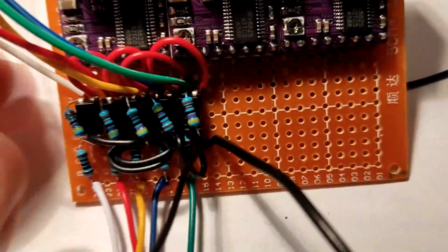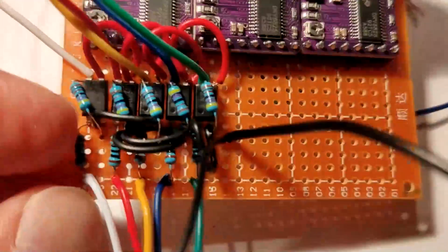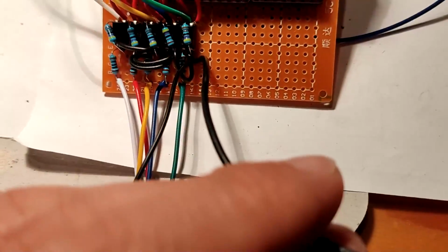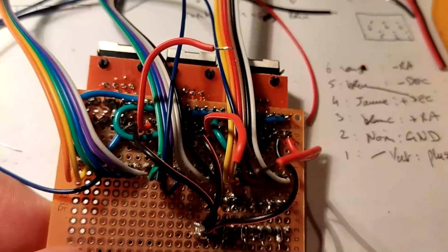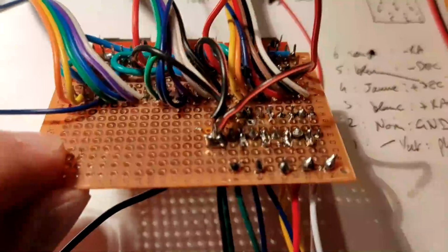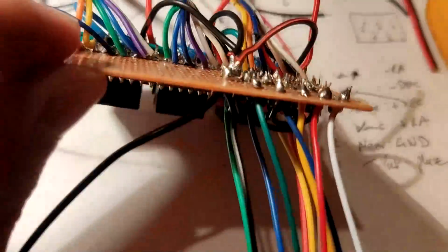I soldered the ground black wire of the RJ12 connector to a place of the board with the big black wire on the same place to make the general ground. At the back of the board I soldered the 3 black wires, the grounds of each driver, to this main ground of the board.